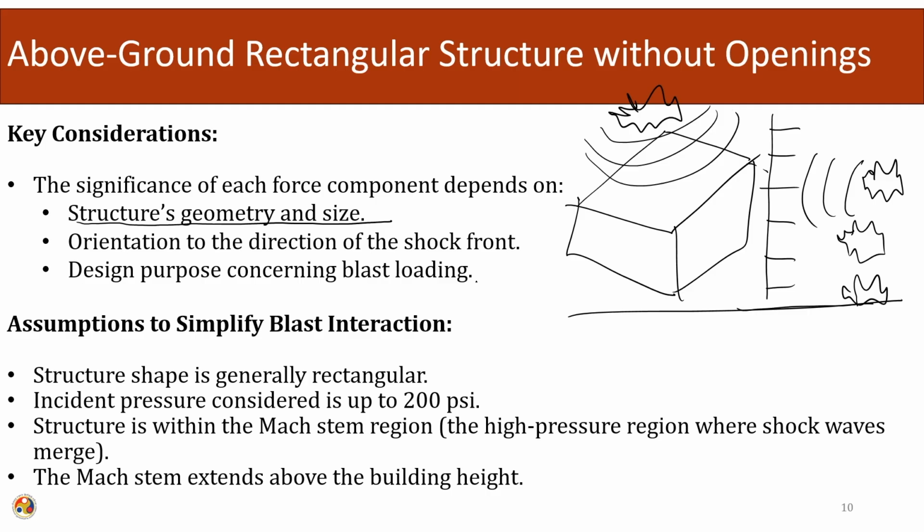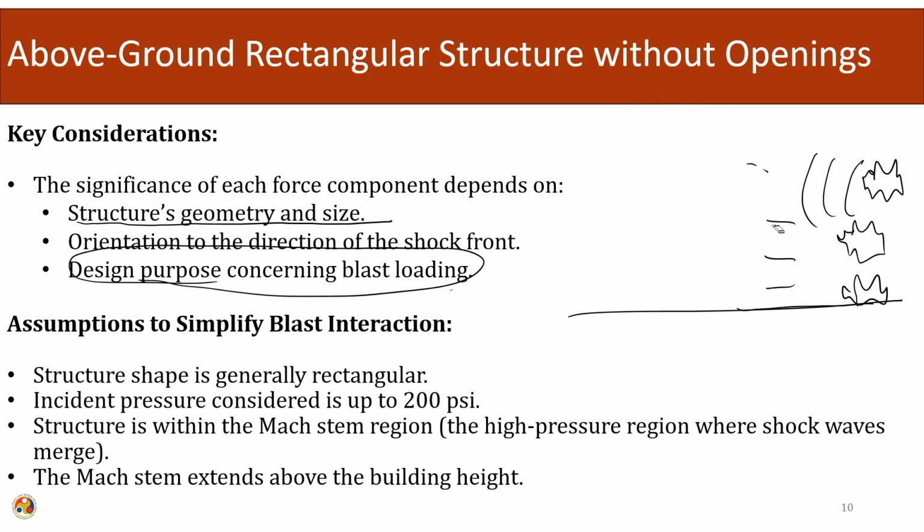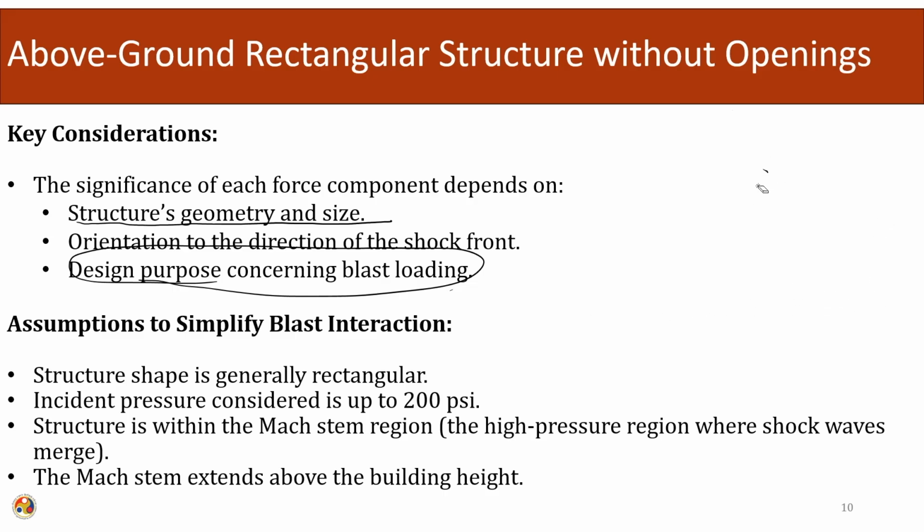And design purpose concerning blast loading. This comes under performance based design. Whenever a structure is designed, its performance normally is fixed. In our conventional design, in RCC design, we are used to designing for the crushing of concrete. In LRFD designs, we have different limit states. In the strength limit state, we are used to designing for the crushing of the concrete or breaking of the bars. This is one of the limit states depending upon the strength.